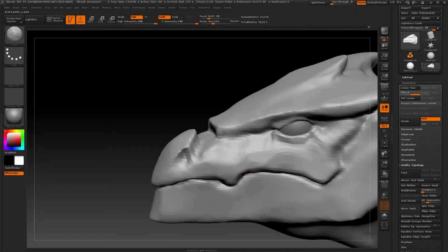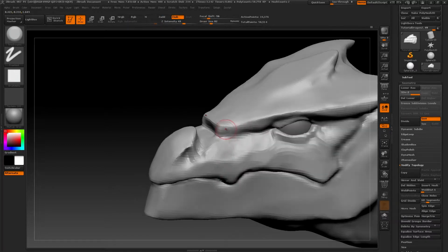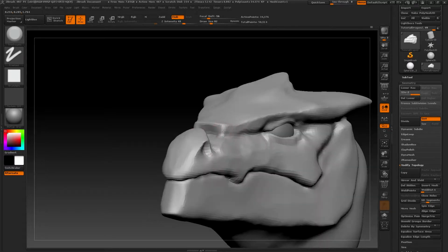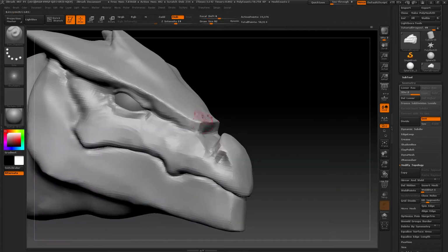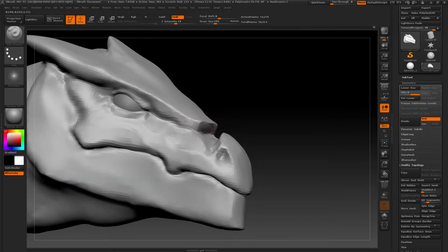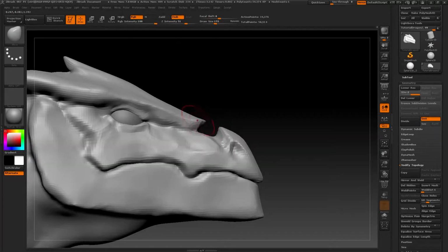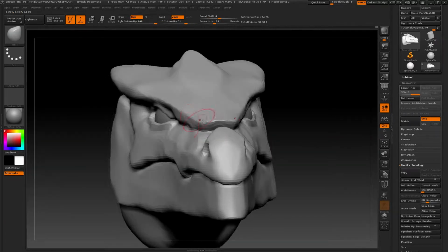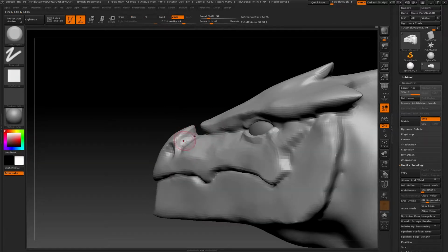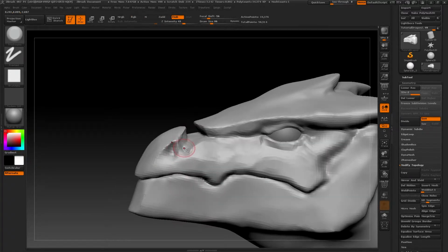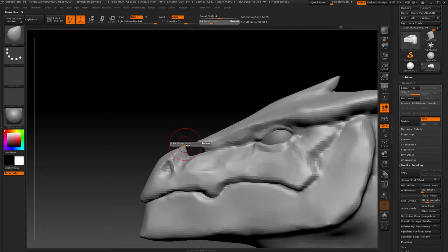We'll use Trim Dynamic again to achieve those hard shapes we got in the previous division. When we subdivide, all the polygons soften, as they go from being flat to having 4 more vertices, which gives them a curve. So after ending up more or less with a harder shape, we'll have to go over it again to get the same effect. But thanks to this, later on, we'll be able to make small adjustments to modify the original shape.